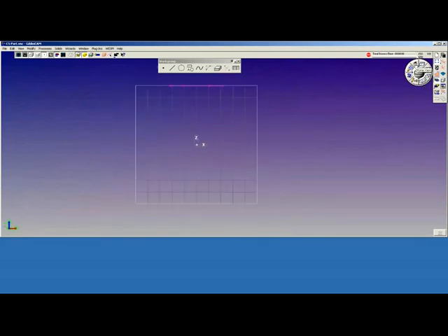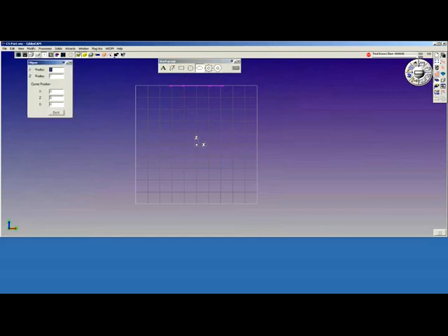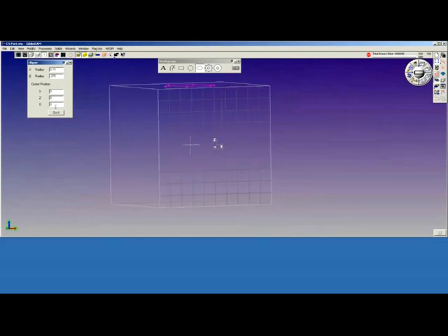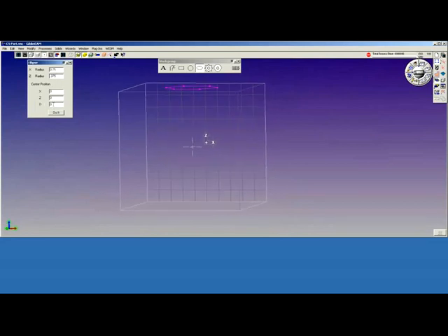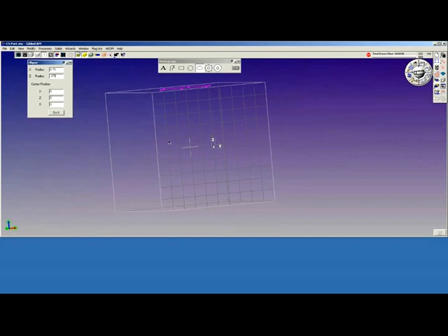By going to the home view, we can then program as if it was laying flat. And I'm going to put some more geometry on there. Let's go with the shape. Keep it simple once again. Ellipse. Let's go next radius 0.75, 0.375, x0, z0. And now you notice that you have a different call letter here. You got a D for depth. The depth axis is always into the work.